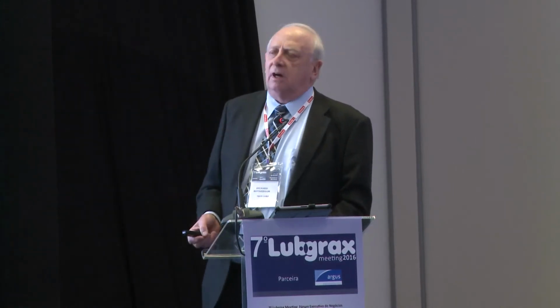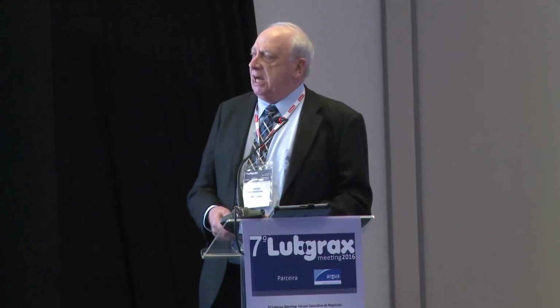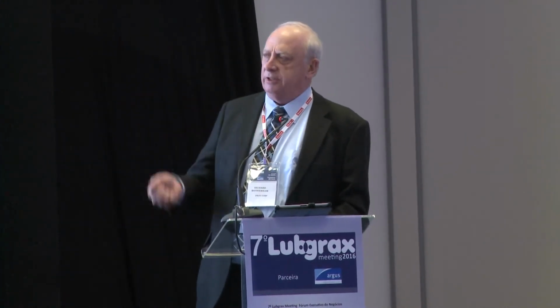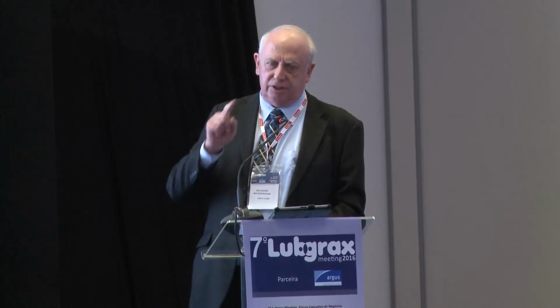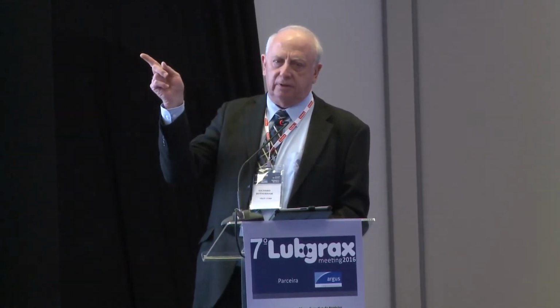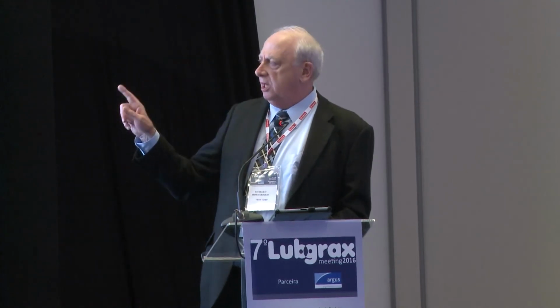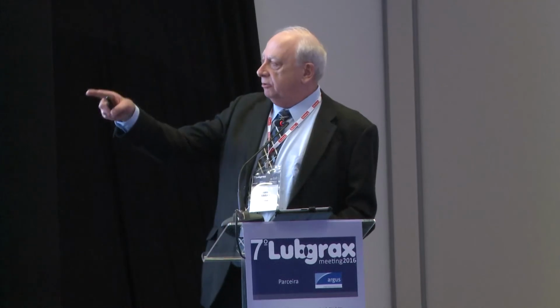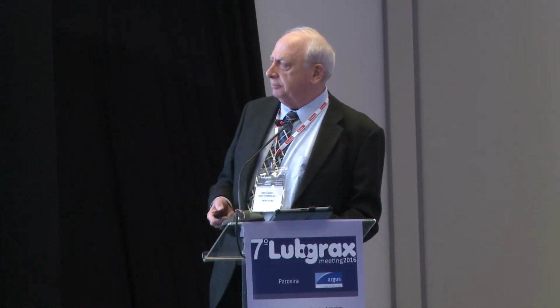Fungal counts are often underestimated. Usually if you're picking up 10 to the 3 fungus or more in a fluid sample, if you go and have a look in the machine or in the system, particularly if you look in the headspace, you'll often find there's very serious fungal contamination. So often be wary about using fungal counts from dip slides. You really need to look periodically.